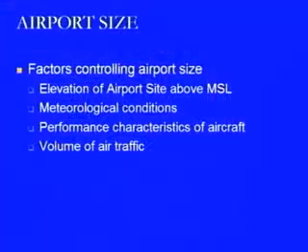Then the volume of air traffic is another factor, because it has an effect on the total number of facilities from where the passengers can be handled with respect to one aircraft. So, if more traffic is coming, then we require more of such places. It means the size of the terminal building will keep on increasing, and as this keeps increasing, the size of the facilities will also keep increasing, thereby increasing the size of the airport.